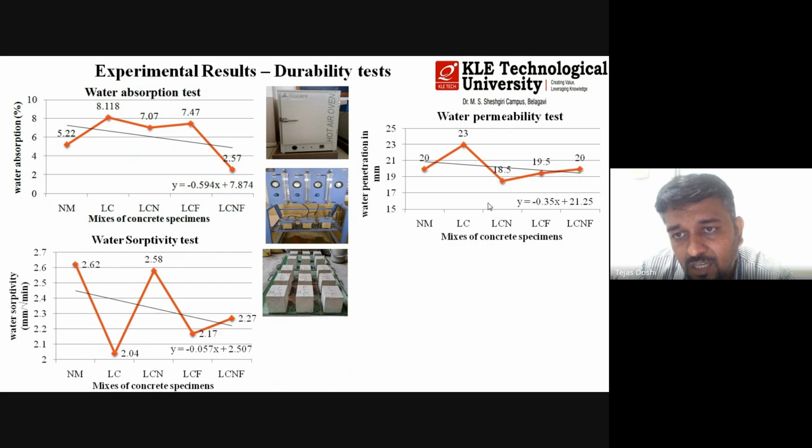The standard water penetration depth is around 25 mm, whereas all the results are within 25 mm. The nominal mix gives us a penetration depth of 20, and LCNF also gives a depth of 20. Therefore, we can say that the LCNF demonstrates a strong resistance to water penetration with a depth of 20 mm, which comfortably meets the acceptable limits.